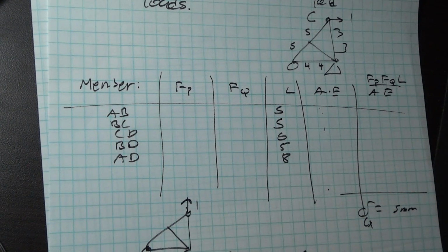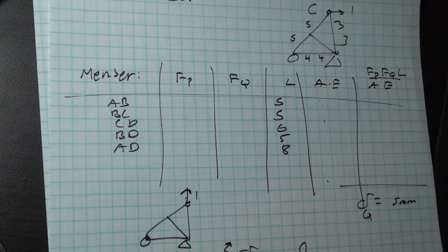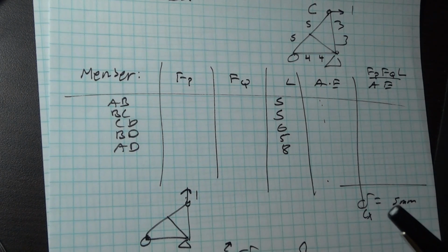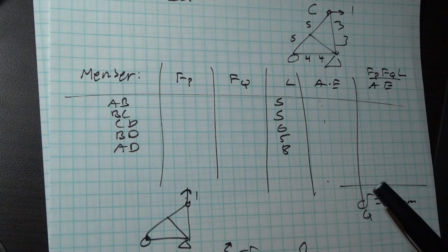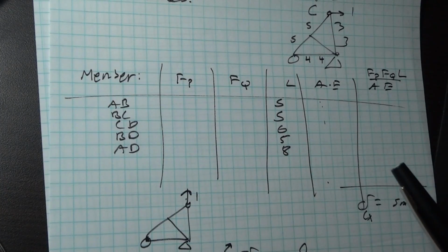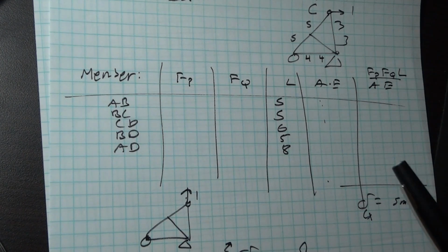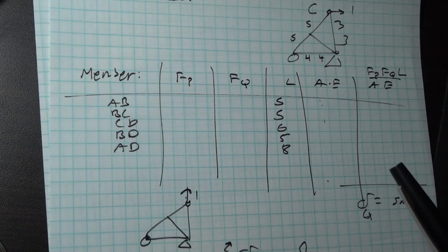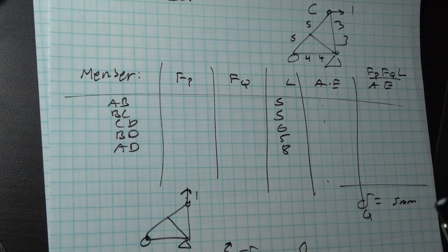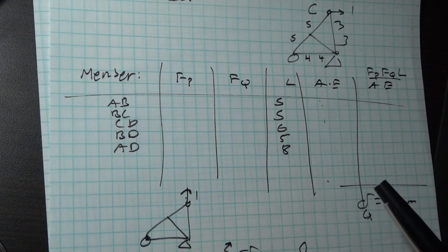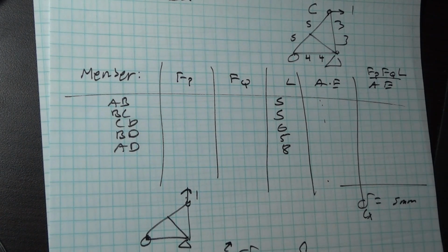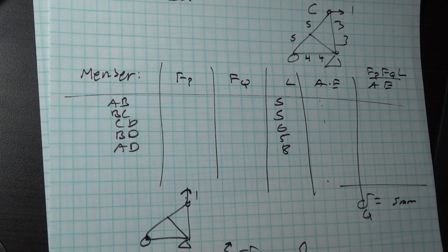SAP is industry grade, so it takes into account a lot of things that we wouldn't normally consider. For example, it takes into account the fact that you're using steel, and there are specific yield points for steel that we don't take into account. We don't, for example, assume that the steel will undergo bolt tear out or block shear. Those are things that we don't take into account in this course. You do take them into account with SAP 2000, so SAP might give you very different results for deflection than you generate here. So that's why I'm wary of having you check actual deflections using SAP.